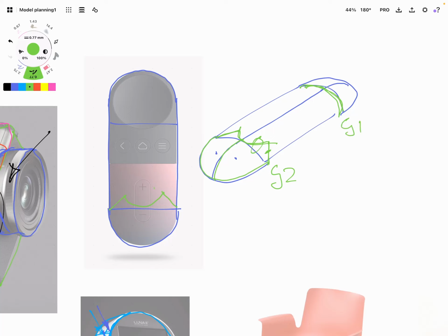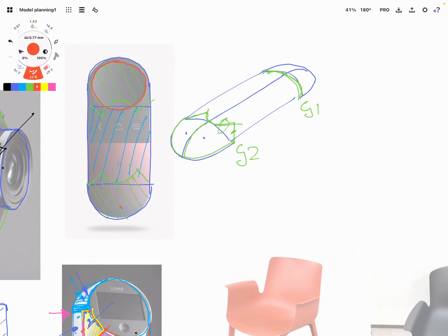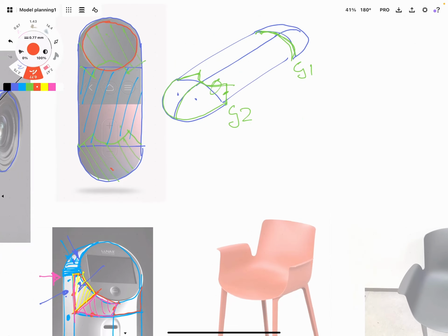Okay, so this form here, I think you'd build the center here, then you build your ends, and then for the recess, this dimple, that curve there, you'll project that on, that'd be the resultant, obviously, where it intersects with the green surface. And then to create the actual dimple, you've got several options there.